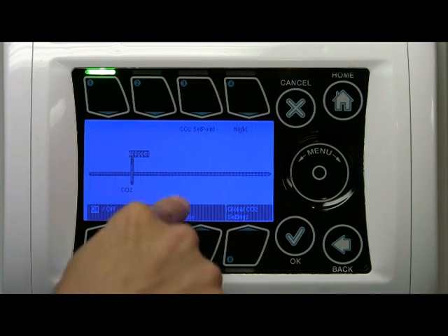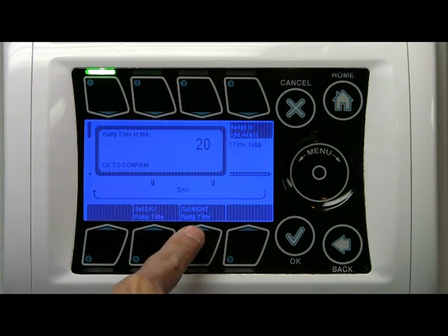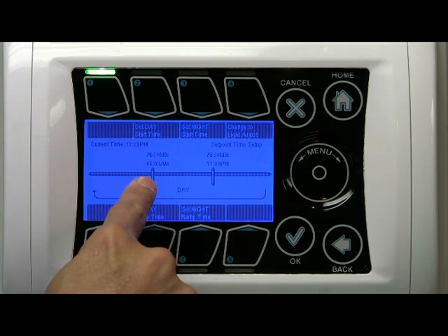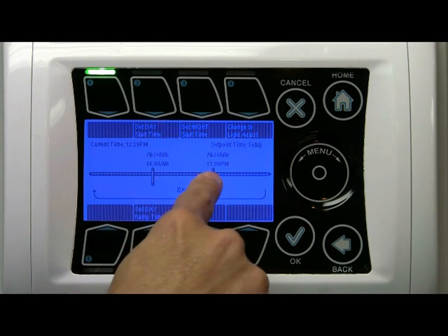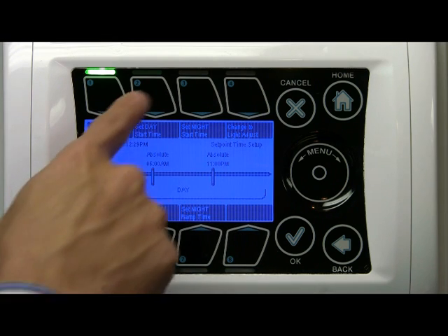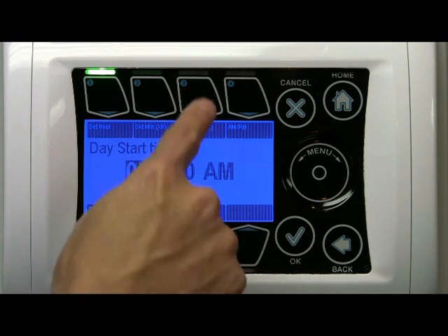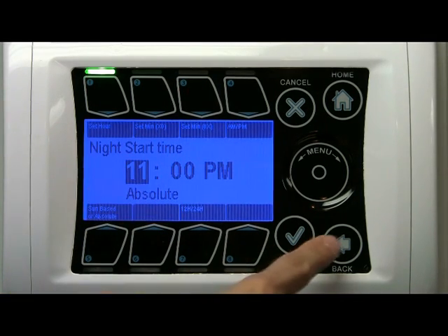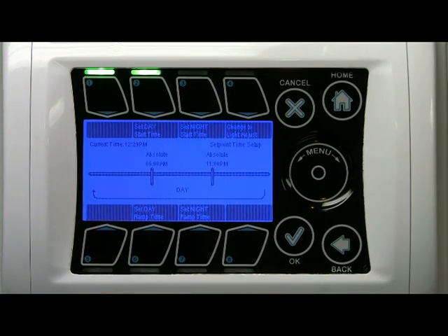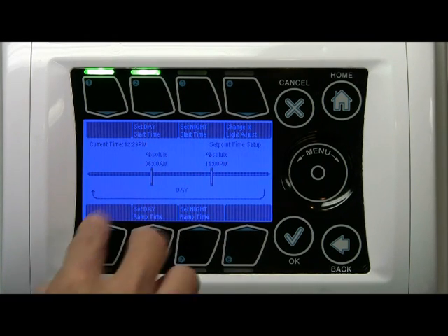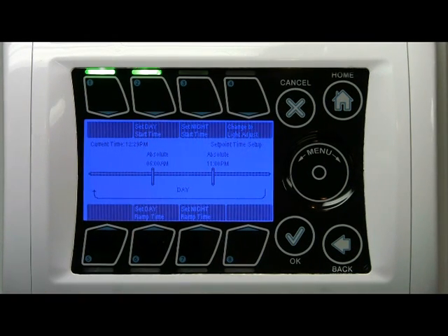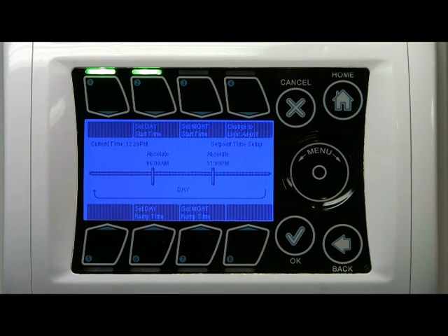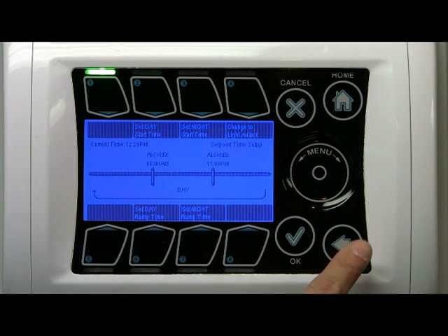You can press this button 7 to set time. Click on that, and here you can set the time to when day starts, 6 a.m., and when night starts, 11 p.m. You click set day 6 a.m. and you can same way click night to set 11 p.m. Go back on it. So between 6 a.m. and 11 p.m. it will elevate the CO2 level to 2000 ppm. From 11 p.m. to 6 a.m. it will allow it to go down to 400 ppm or lower.